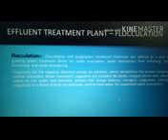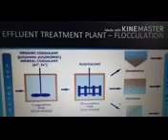Coagulants kill the negative electrical charge on particles, which destabilizes the forces keeping colloids separated. The water treatment coagulants are positively charged molecules that, when added to the water and mixed, achieve this charge neutralization. Inorganic coagulants, organic coagulants or a blend of both are commonly used to treat water for suspended solids removal.